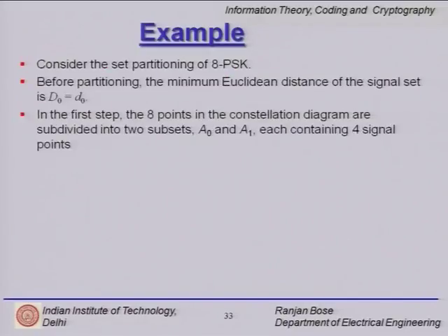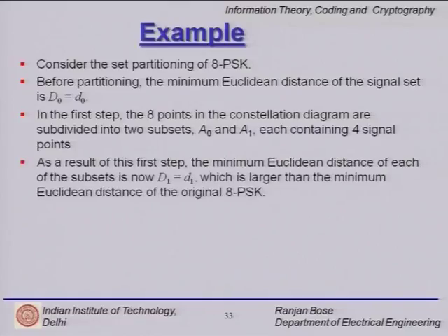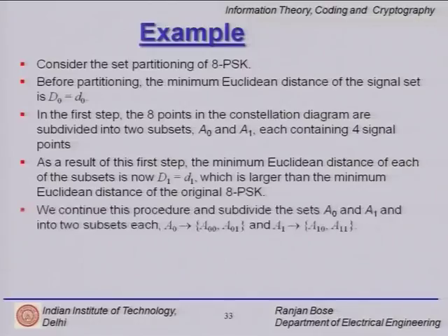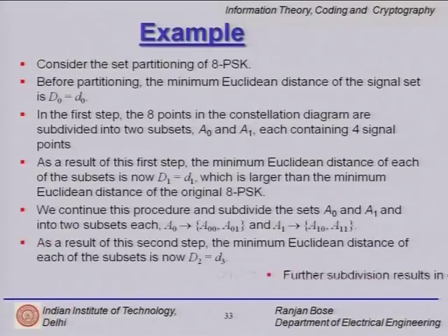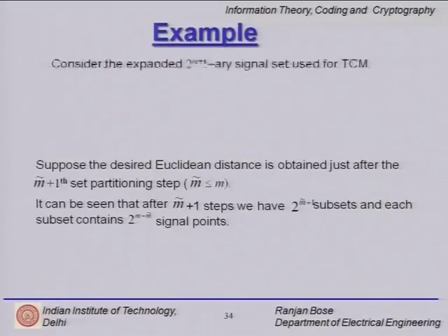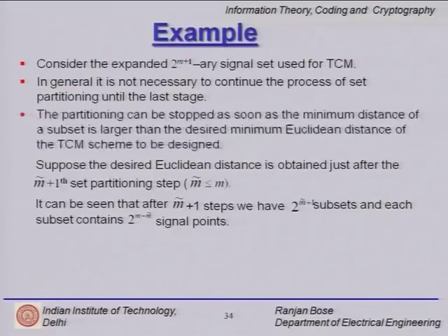So, now the aim is how to use this partitioned set and map it to the trellis that we have here. So, what we do is we basically come up with a rule as to how to apply these points from the different levels of the constellation diagram, because the level decides what is the minimum distance in terms of the diverging and merging paths. Okay.